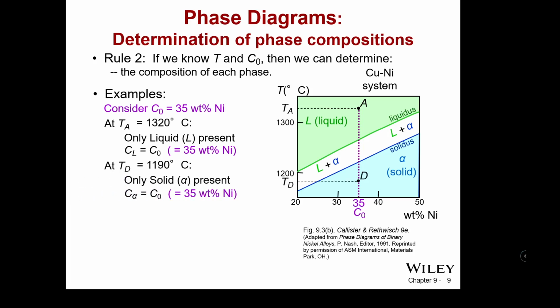If we cool it to 1190 C, that same material exactly, we know we're going to have only alpha, so it's going to be all solid. If we bring it back up to temperature 1250 C, we're going to be right in that middle region where we're going to have both alpha and liquid present, because we're inside that phase change envelope.